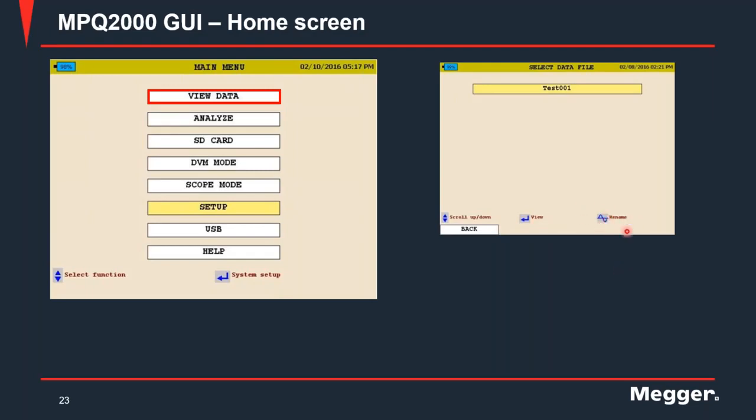Here it's basically asking you to press the scope mode shortcut key to rename the file. When would you use it? Let's say you have to record at multiple locations before you can download the data onto your software. In that case, to be able to differentiate between files, you can rename the files on the unit itself.